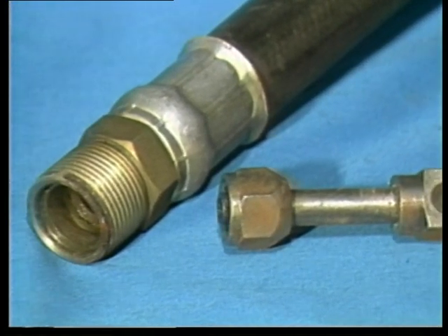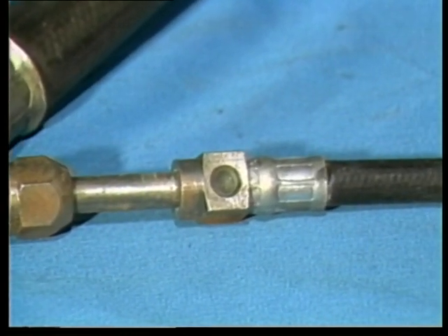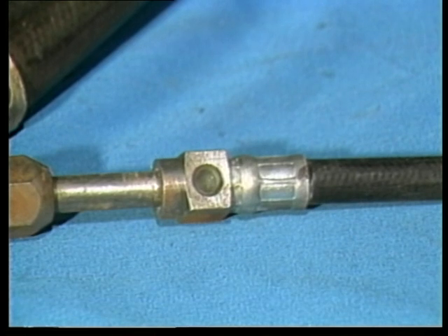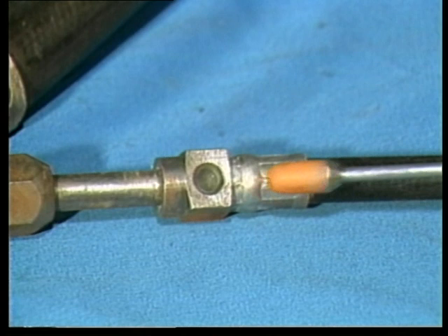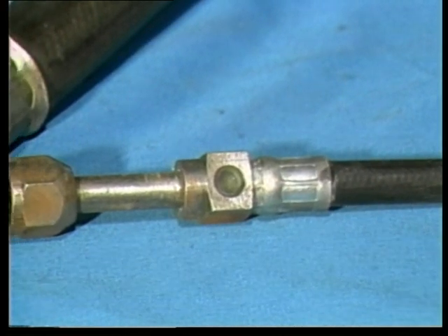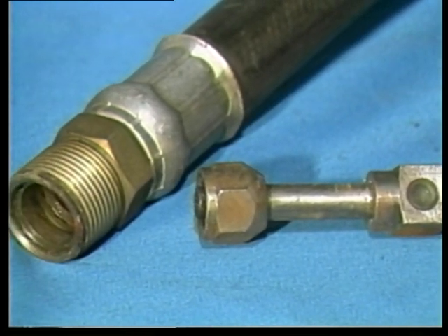Refrigerant lines and hoses are normally designed to withstand up to 1,500 pounds of pressure, even though normal operating pressure averages about 200 pounds. Note that a sight glass is provided in this refrigerant line. It allows you to check general state of charge in the system.